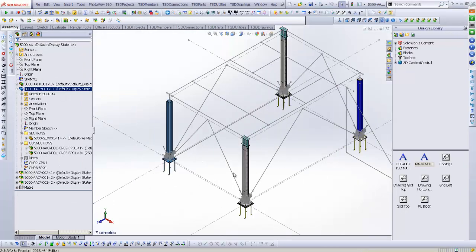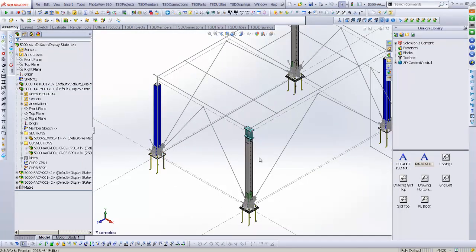Now what we want to do is lock this column. Because now that column's been done, we want to lock this column. From this point on, it means that we can now lock any member in our project, and our automatic mark numbering will come into the drawings, apart from the mark note and the balloons, which has to be done prior to using or creating in your projects in your library.